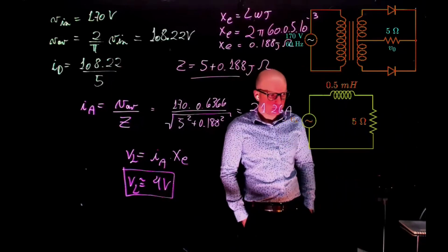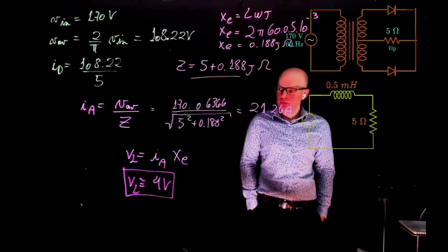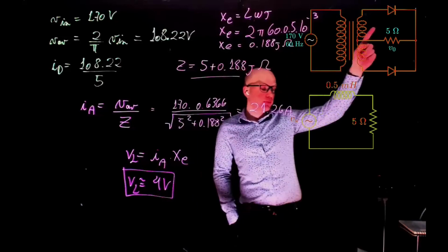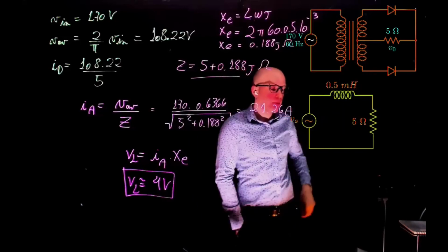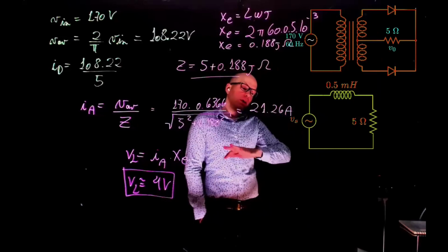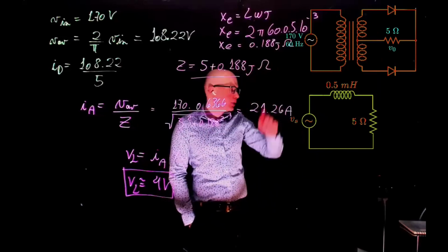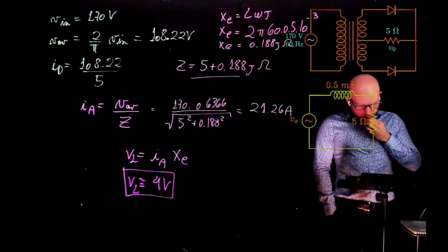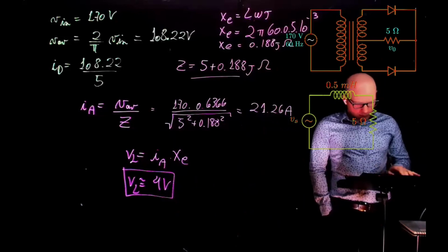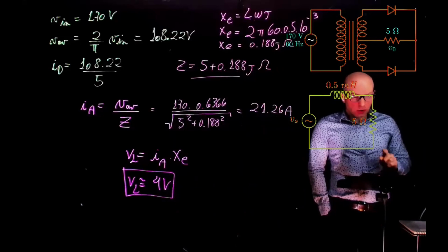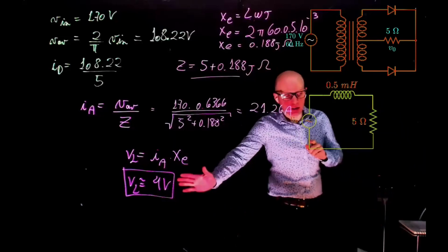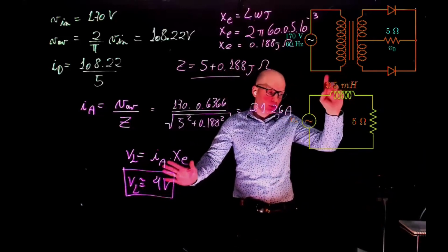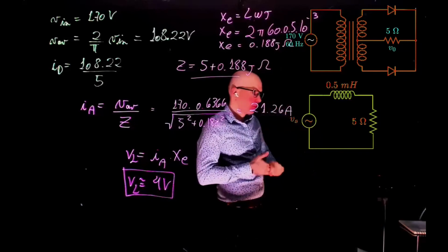Just a quick question. In this example, we're pretending it's an ideal diode and that there is no drop in the top, right? Exactly, because otherwise we would need to account for a 0.7 volt drop there every time. Good question, because now I compared this with the full bridge. So we would need to account for 0.7 volts drops there. This 4 volts is only across the inductor, the average across the inductor. Then each diode would be an additional 0.7 volts. Okay. All right.